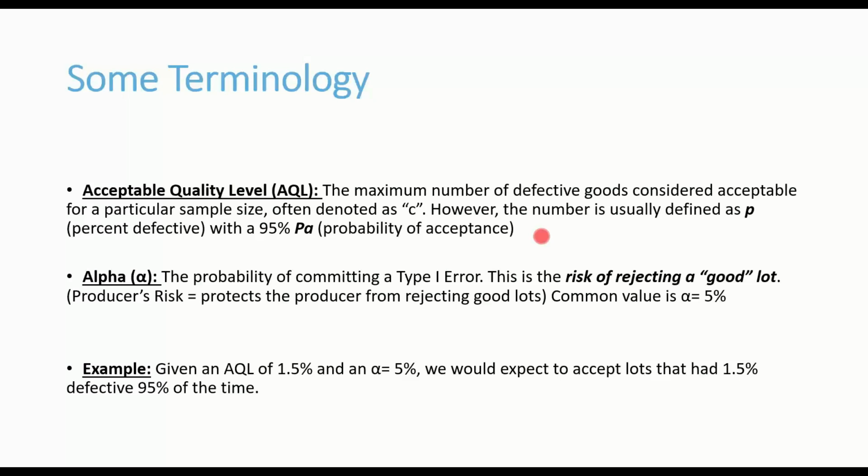Okay, the AQL is defined by both the producer and consumer prior to any pre-shipment inspection. Defects and defectives are also defined by both parties. So I have an example here. If we have an AQL of 1.5%, which is rather high if you're in medical or pharmaceutical, but that's what I use today in most of the examples.